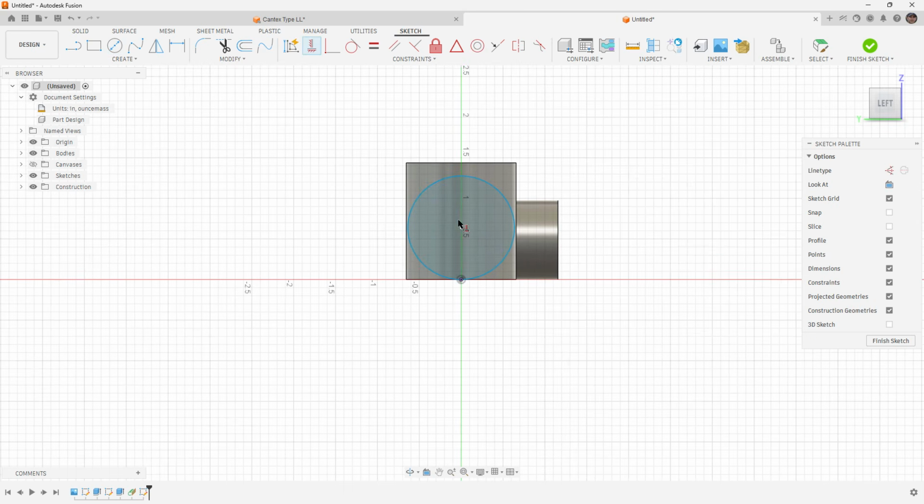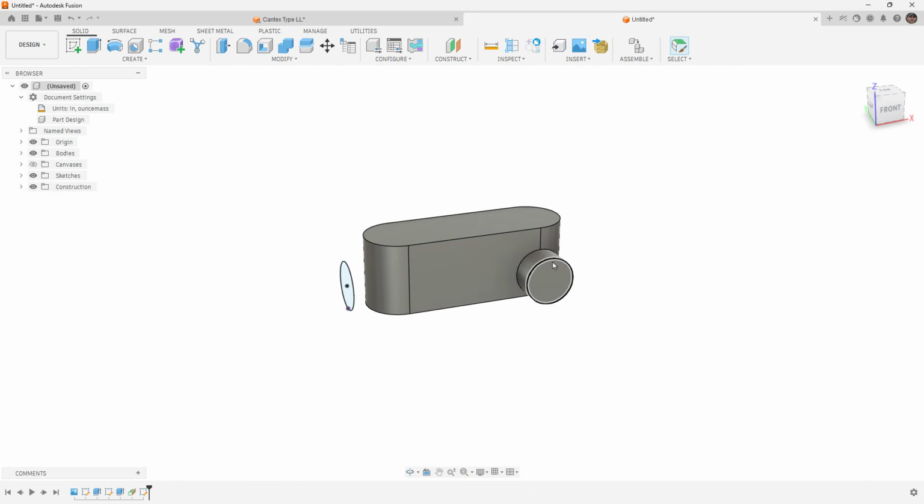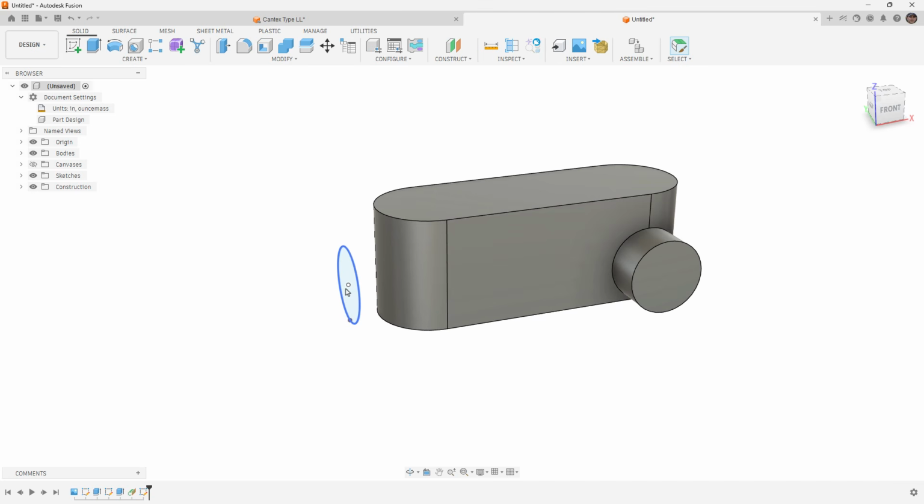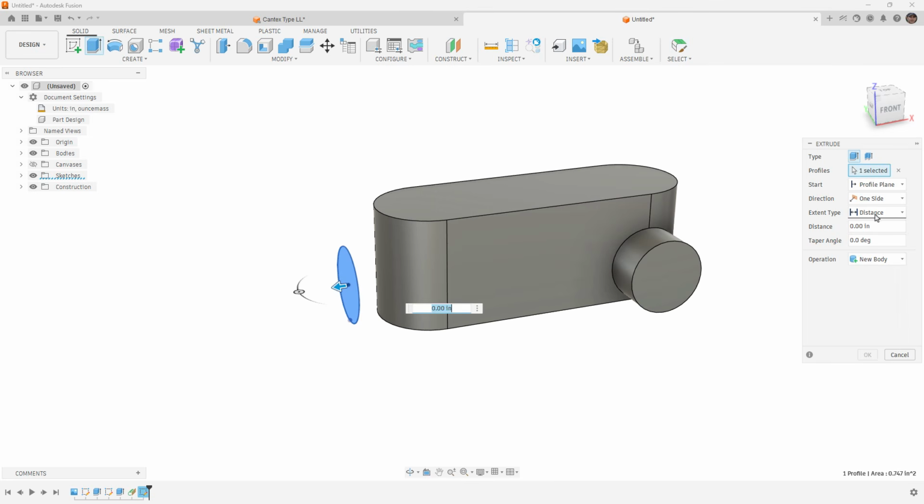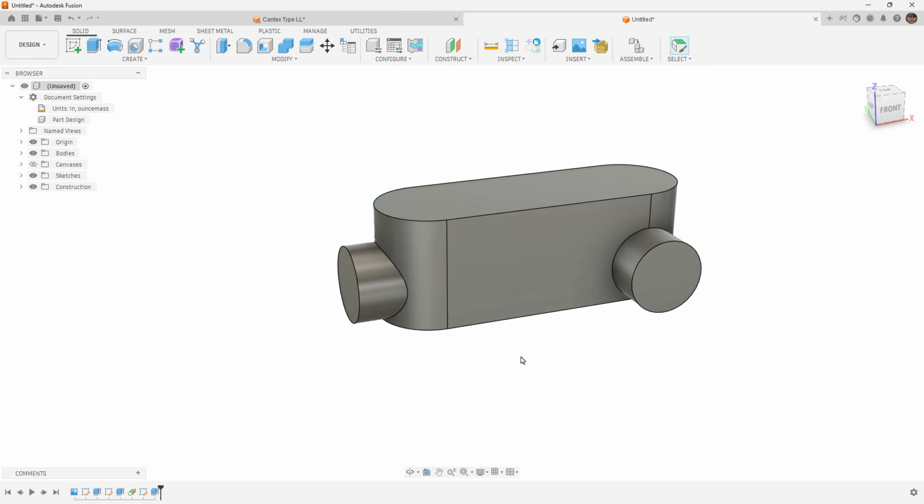We need to make sure that this is vertical above the origin, and then we need to give it a dimension. This is going to be our dimension E again. So that's that diameter plus the wall thickness. Hit enter, and now we've got the correct size. There are other ways that we could go about this. We could make it equal to that other dimension, but with everything linked back to those parameters, we don't have to worry because it's all going to be changed in one location. Then in this case, I'm going to extrude this to object. I'll select here, join them together, and say OK.